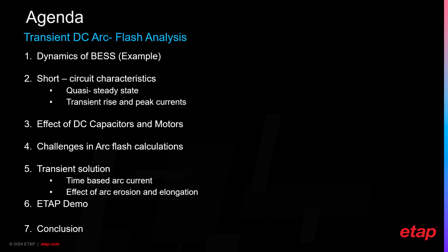In the previous part of the session, Walter briefly described the probabilistic variations of the equipment, the short circuit characteristics, and the maximum and the minimum short circuit current, and how it is being used to determine a constant energy area in order to evaluate the operation of the time current device.